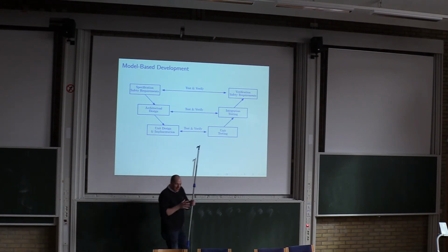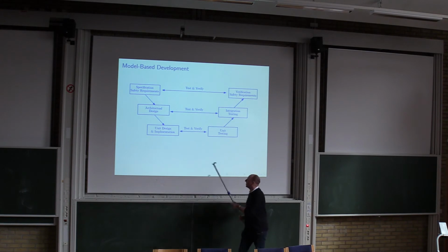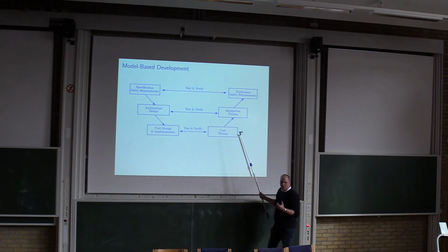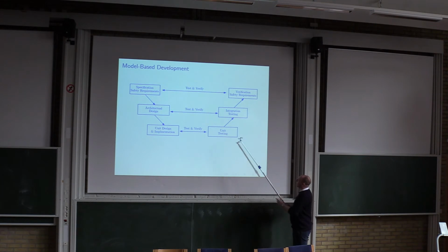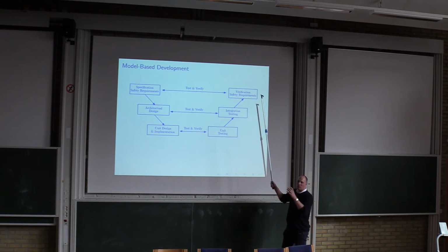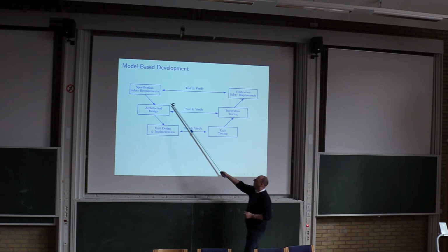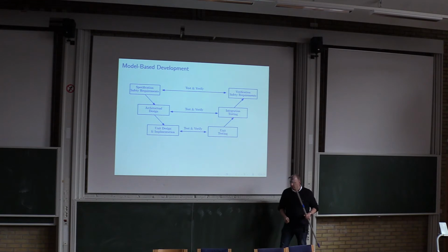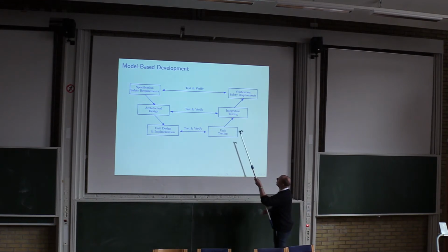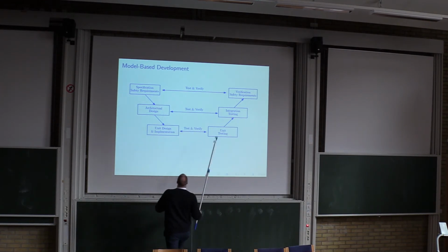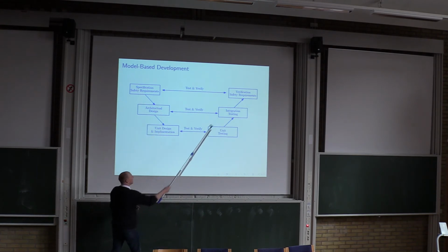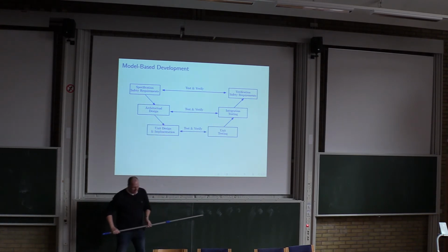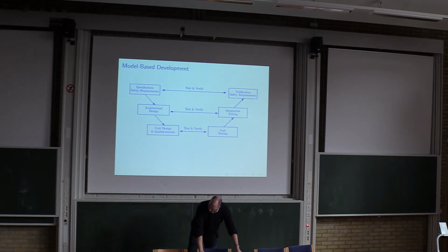So you have defined all your small components, control algorithms, etc. Then you try to test them separately. And then you try to combine them together and test whether the interaction is all right or not. And then you put that in the whole system, and you check against the original specifications that you set up on your closed loop system. So this way of doing the design and the testing is called the V model. You've probably heard about it before.